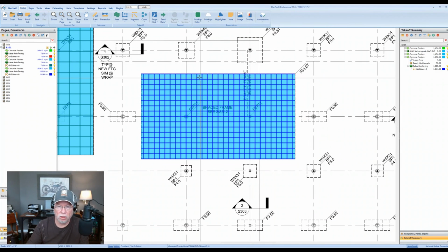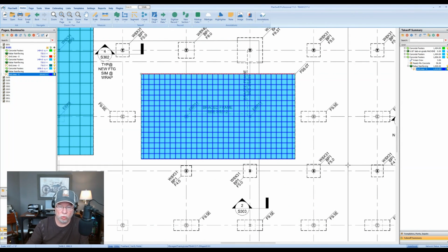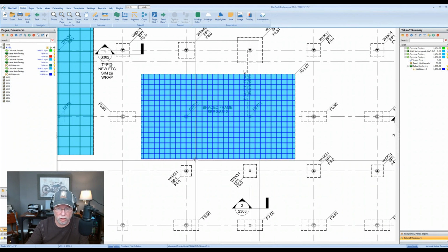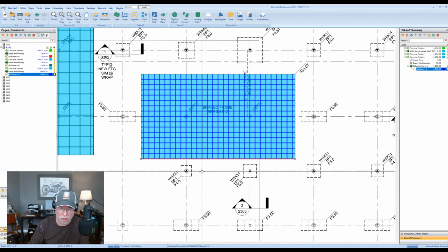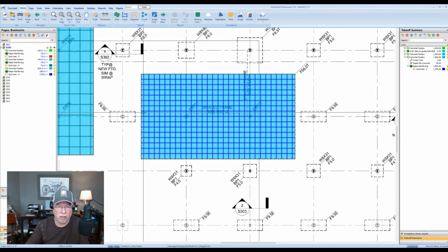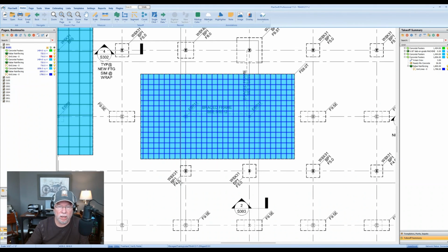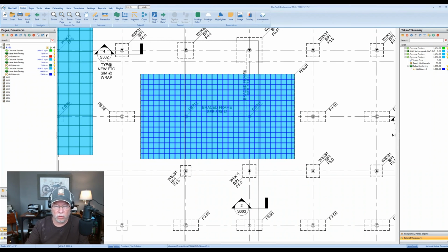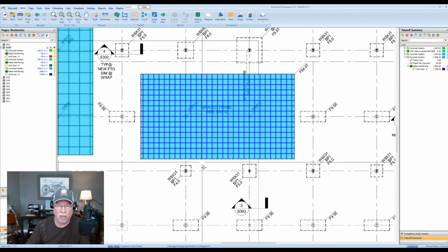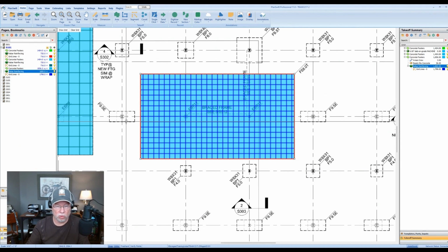We don't like the color, we change the color. Sometimes it will draw lines where you don't need it. So draw the line on the end, so I'm going to delete that line. It drew one down here too. I don't need that line. I can add or subtract lines in the grids. So don't feel like you're stuck with that. As long as you don't click on redraw grid, where it redraws everything, you can add or subtract any number of lines you want to.